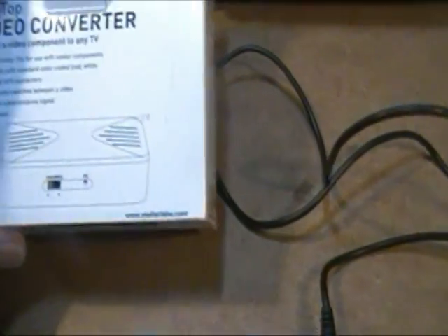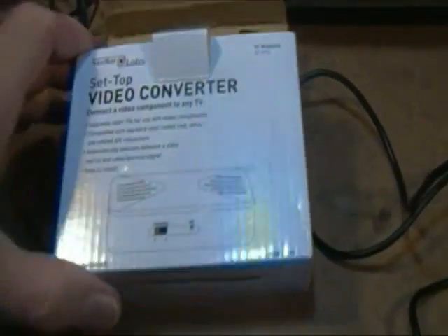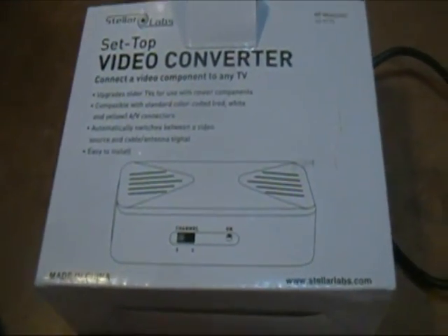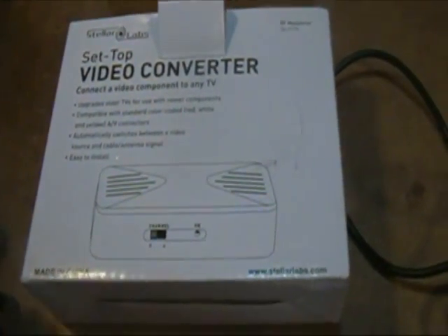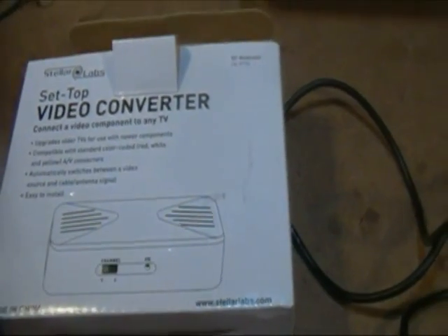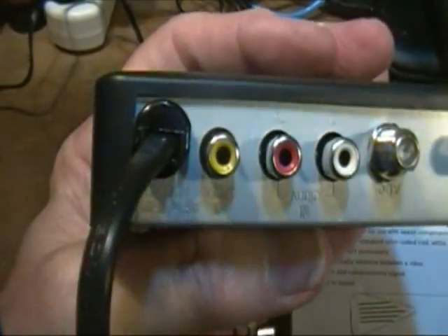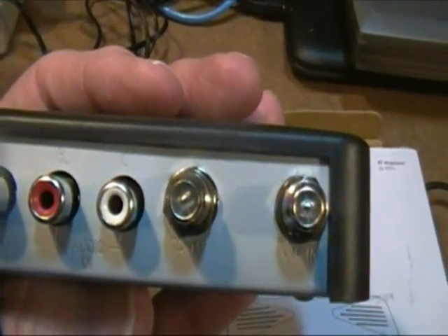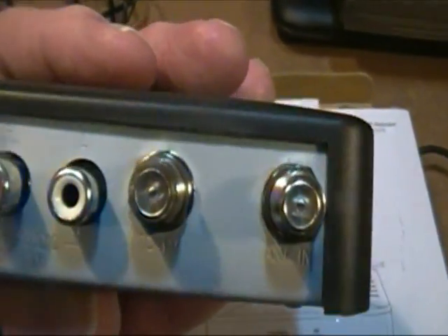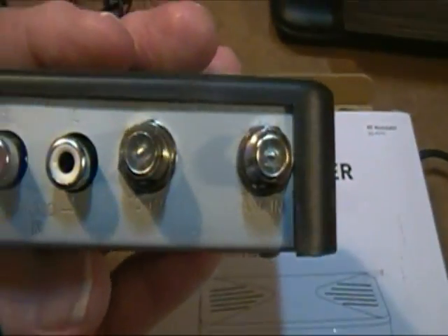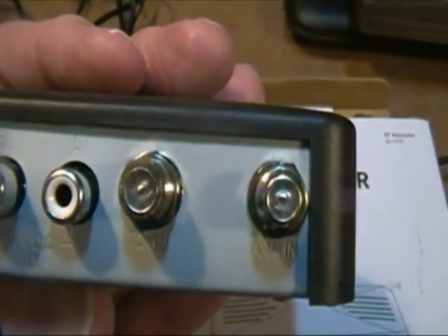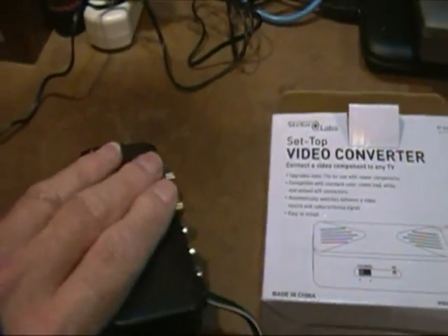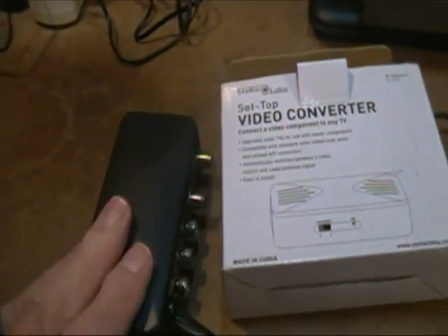Also, for completeness, I suppose I should mention that if you have a real old TV that doesn't have any input except just the antenna connection, you can still buy these video converters that will connect basically the old AV and analog audio and convert it to an RF signal that you can then connect to your TV set. In fact, in the early days of VCRs, most of them started out with this as the connection mechanism. Now, the problem with this, of course, is that it has much lower definition and is more subject to interference and